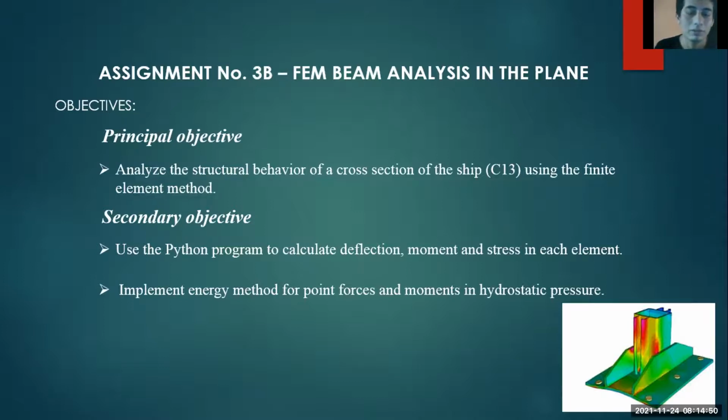It uses a matrix formulation for solving algebraic equations. It uses first bars, and second beams. The first step, the bars, analyzes only the axial direction, and the second step, the beams, analyzes the force in the transversal direction and moment. In the case of the project, we combine the bar and beam elements in a stiffness matrix to find the result and the behavior of the elements.